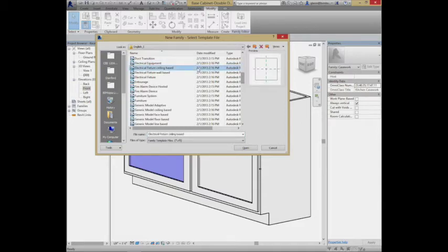If I'm designing a lamp that's going to sit on a table, I would probably do that as just an electrical fixture, because it could sit on pretty much a table anywhere in the room. It could sit over here, it could sit over there, a floor lamp, same sort of thing. I could set it anywhere. It's not really hosted by anything. It has complete flexibility about wherever it can be. So things that don't say based, you're just going to put them anywhere you want to. You have complete control, X, Y, where you want to put them.